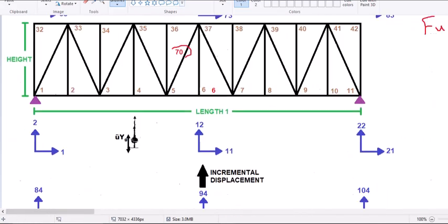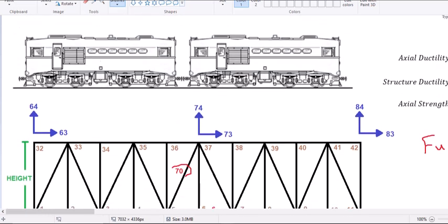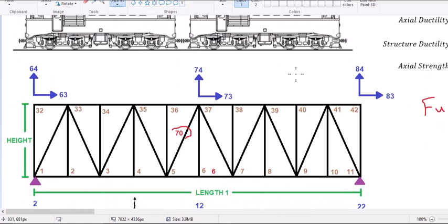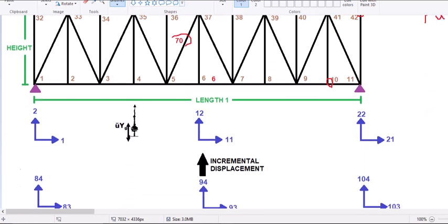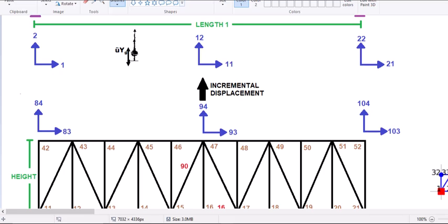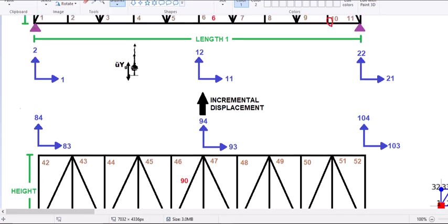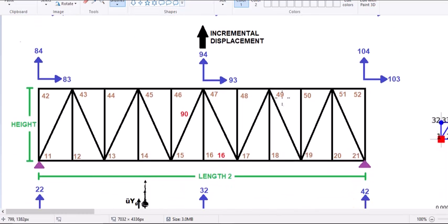If we go back to the response spectrum analysis, we're going to add the mass at each point of this structural node as a two-dimensional model, and run the nonlinear dynamic analysis with the vertical accelerations and vertical incremental displacement. So at each node of these elements we have a constant mass of these values.